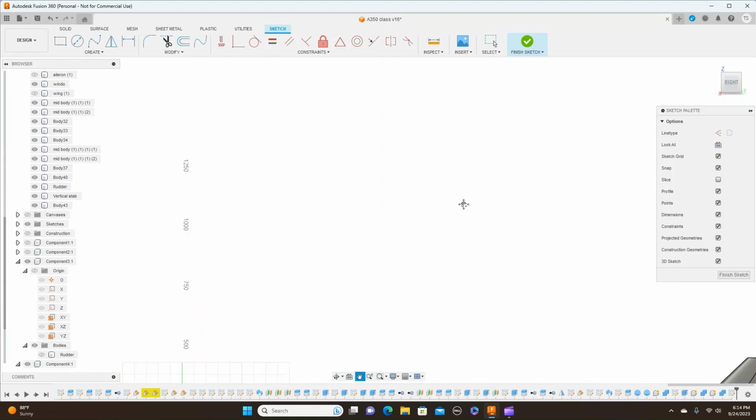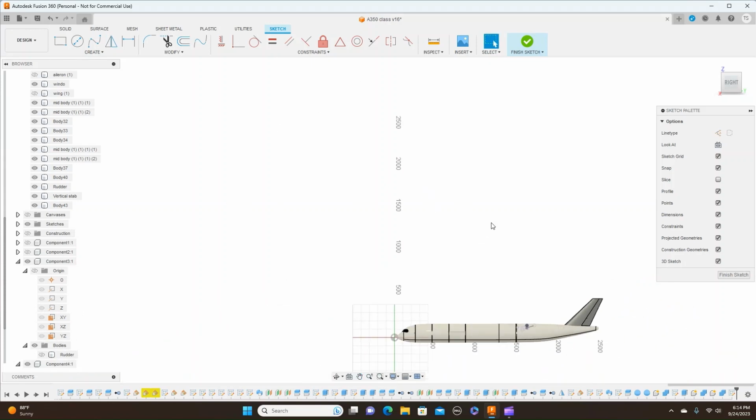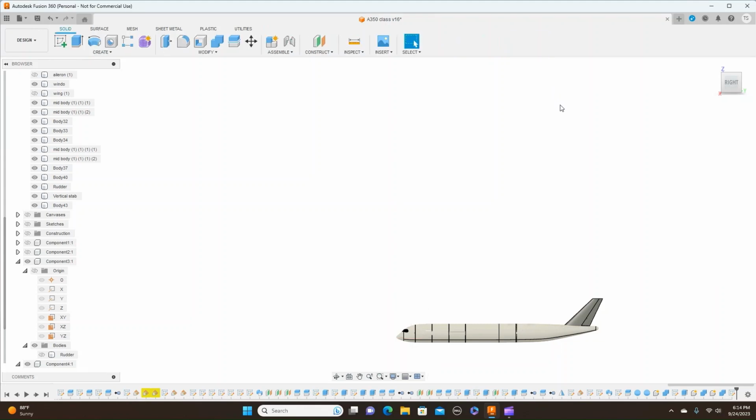But it's rather tiny compared to that. So again, what you want to do is just draw that 14 by 15 millimeters. And then the thickness of that hinge is just slightly less than 1 millimeter. So you could set it at 0.925 millimeters to thickness, and that should give you enough leeway of putting that hinge in there. But anyway, that's it for now.